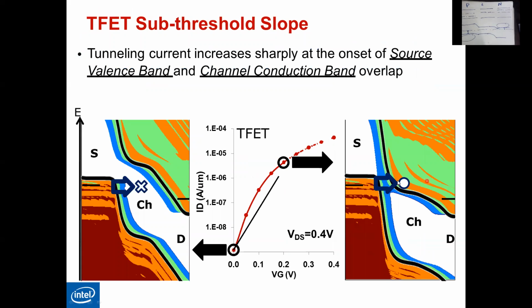So as you can see, after applying a voltage, this is at 0 voltage, you have a huge channel or a huge gap. Whenever you apply the voltage, the gap becomes narrower, so electrons will tunnel faster. Whenever you decrease the gap, electrons will tunnel faster, and that's why we have a higher current here, which is the comparison between a lower voltage, which is typically 0, and a higher voltage. So the voltage here actually controls the distance between the source and the drain.